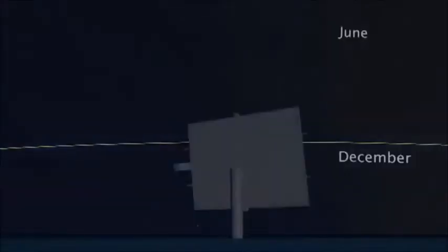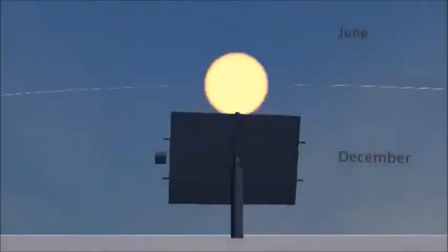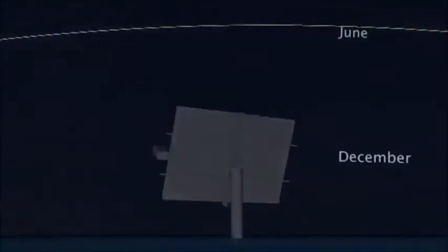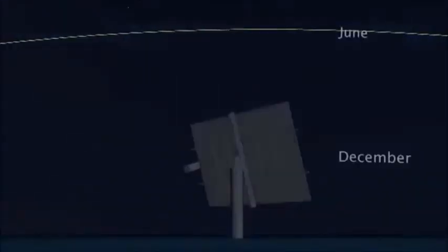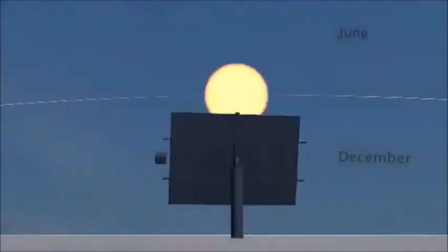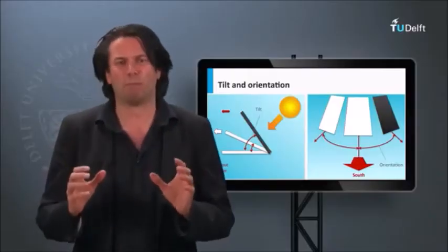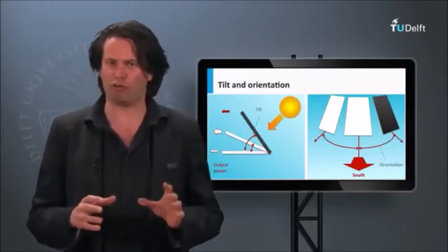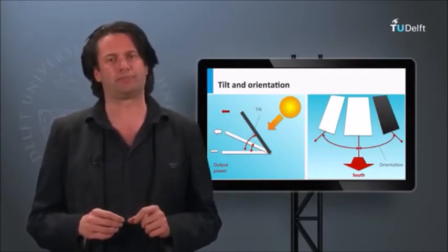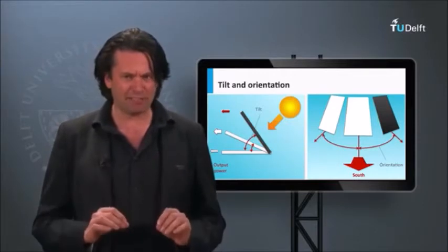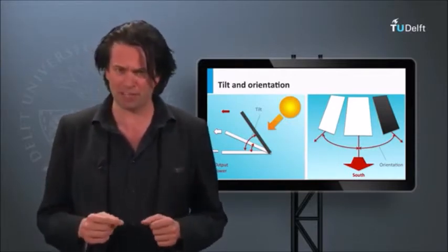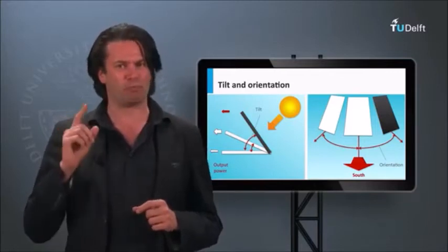Its effect is that in June and December, the Sun is closer to the northern and southern hemispheres' mid-latitudes respectively, while in March and September it's closer to the equator. Thus we see a need to vary the tilt of the solar panel. This is exactly what is shown in the video, that the tilt of the solar panel is changing as the year progresses. Now, most solar panels or systems don't have the luxury of employing a dual-axis solar tracker. Not only are they very expensive, they are also difficult to implement if the panels are to be mounted on the rooftop.